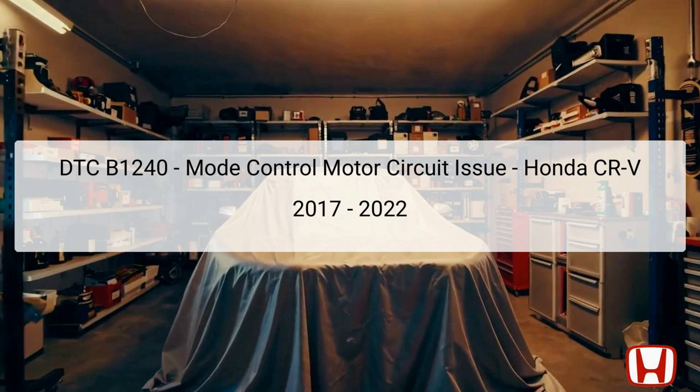The Diagnostic Trouble Code DTC B1240 indicates a potential issue with the mode control motor circuit, linkage, door or motor itself in the Honda CR-V 2017 to 2022 models. The mode control motor is responsible for regulating airflow within the climate control system, directing air to various vents based on the driver's chosen settings.